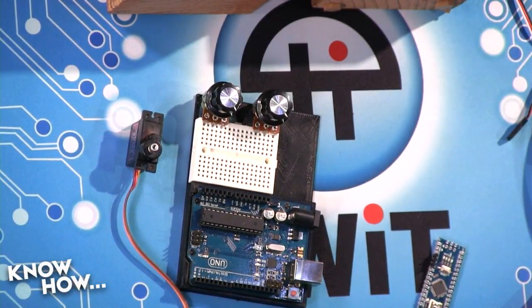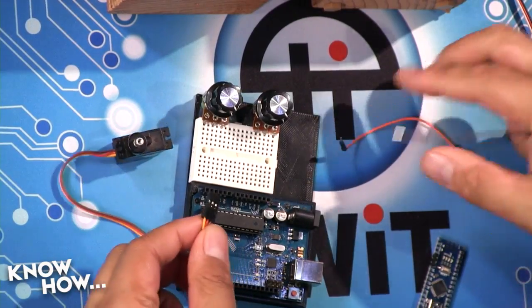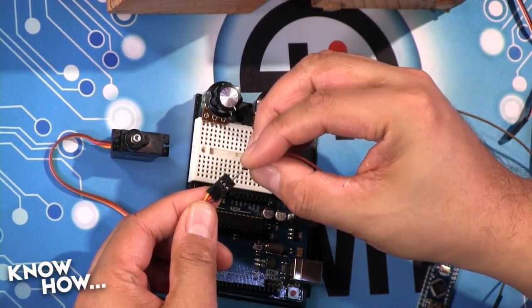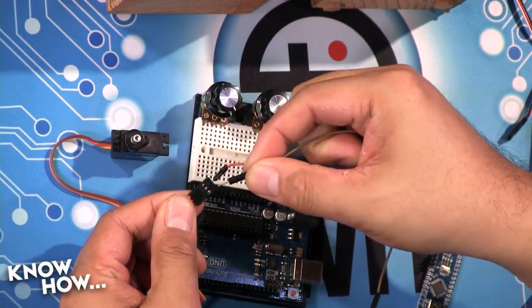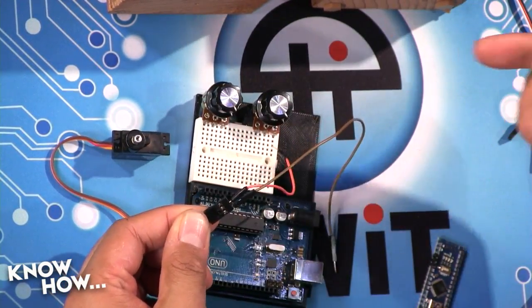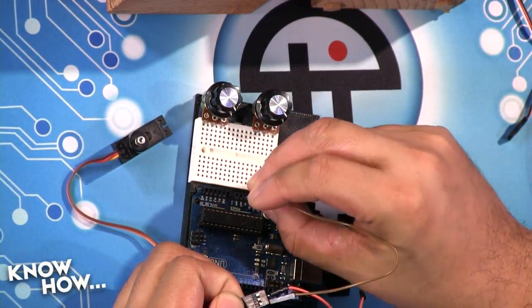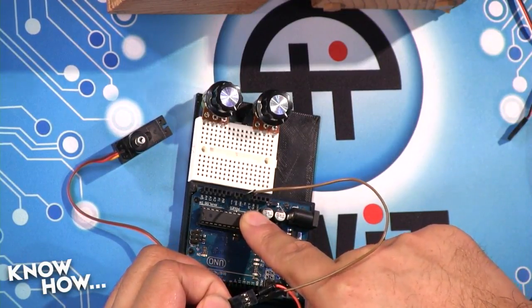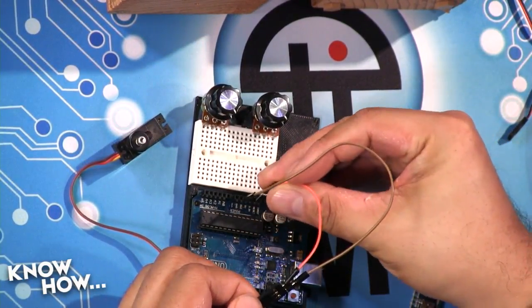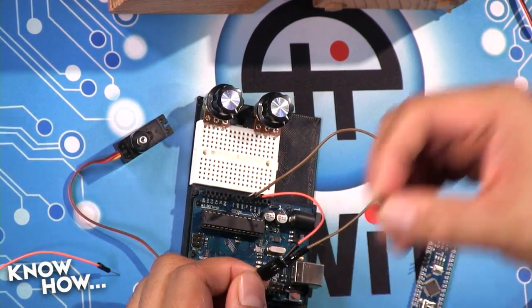All right, so here's what we're going to do. I'm going to use jumpers. Here we go, little jumpers. So I need power. I'm going to take this orange one and put it into the center pin, which is my 5-volt voltage. I'm going to take this brown one and put it into the ground because I need to get ground out of it as well. Right. And remember, when we did our Arduino projects, these are all labeled. So that's labeled GND for ground. This one is 5 volts, so I'm going to put it into the 5-volt line. They're right next to each other.